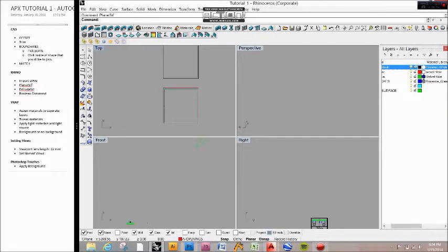But I want to know exactly how high I have to extrude that wall. That's what I'm going to need my section for. Now sections have to be tilted 90 degrees so that you can measure it in your space. So you have to rotate it in 3D. There's the rotate button over here, and you have to right click so that it's rotate 3D. Right click it. Select your rotation axis, and then just write 90.